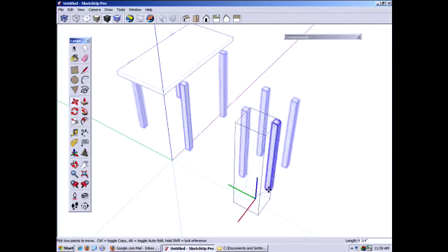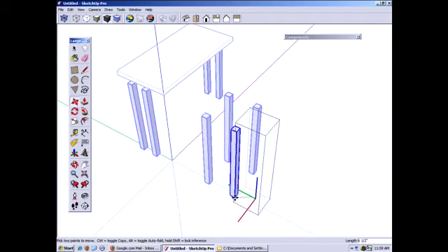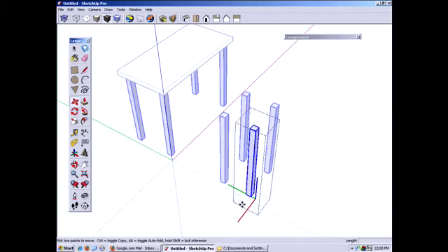Whereas you can see the legs under the table, because we inverted them, because we mirrored it this way and then we mirrored it this way, we got the behavior we want. So anytime you're building something like this, and there would be many things like this, mirroring it from the start and building in that component is going to be very beneficial to you. Yes, it's very crucial that you invert them, mirror them, however you want to say it.